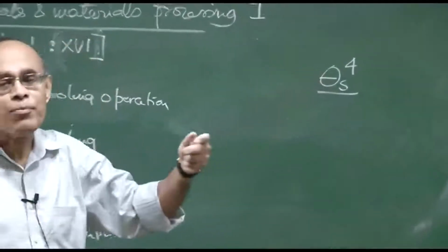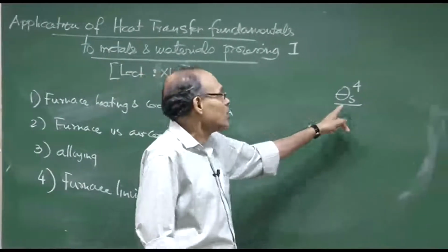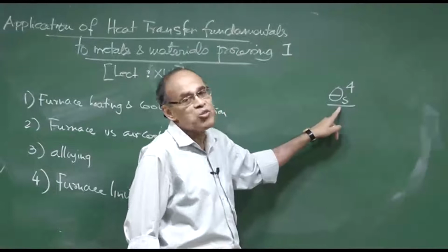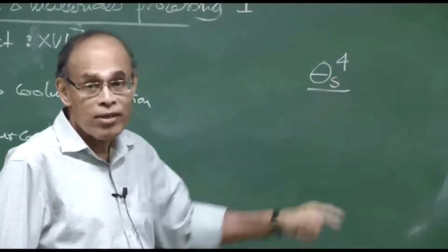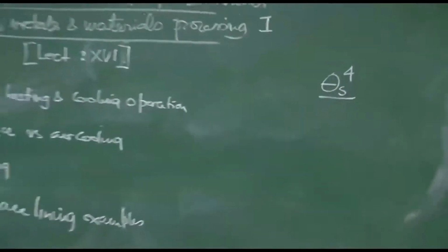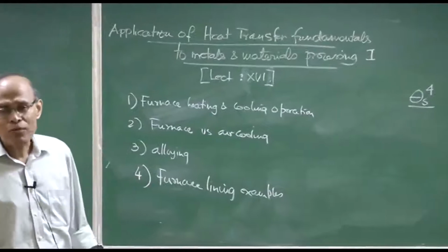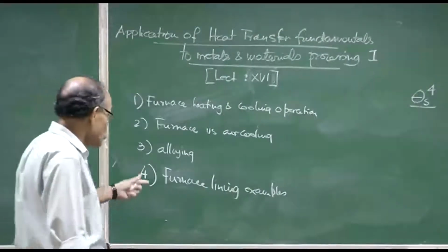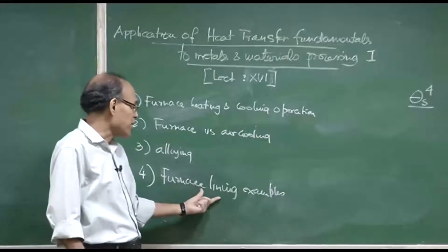product. If you can imagine a product coming out of a continuous casting mill, the slab has a surface temperature of about 1000 to 1100 degree centigrade, and in that case you can imagine, raised to the power 4, therefore, how large should be the value of it. So, furnaces also are maintained at very high temperature, 1000 degrees, 1200 degrees, 1400 degrees sometimes. So, the furnaces need to be lined with insulating material, high grade insulating and refractory materials.